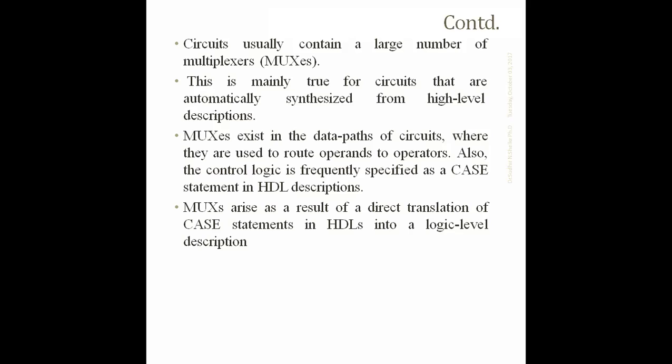Also, control logic is frequently specified as a case statement in the hardware description language. The MUX arises as a result of a direct translation of a case statement in HDL into a logic level description.